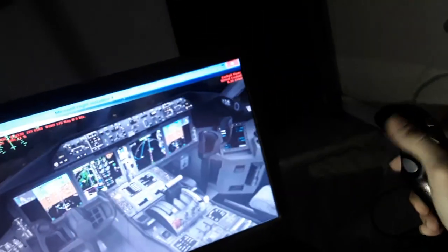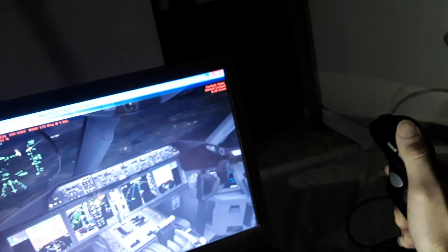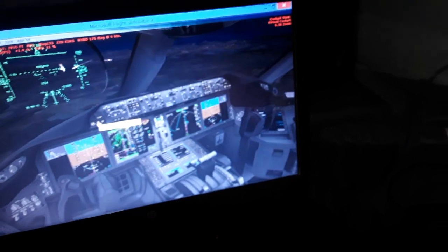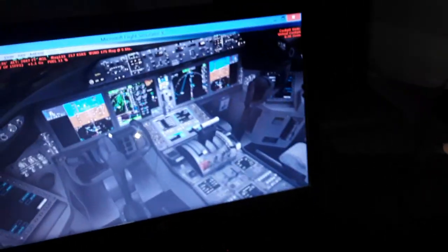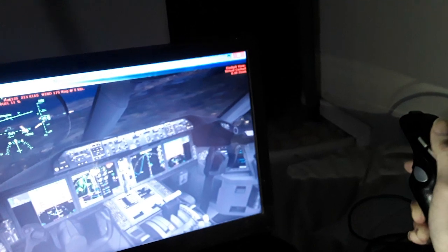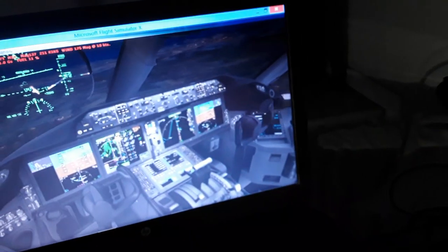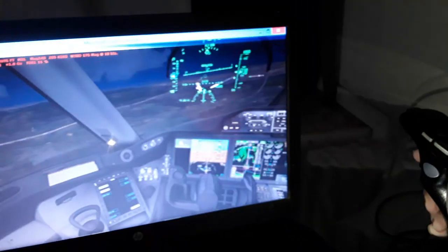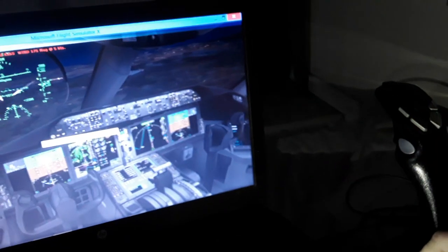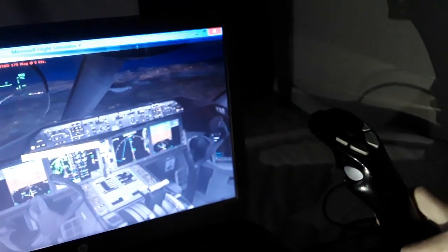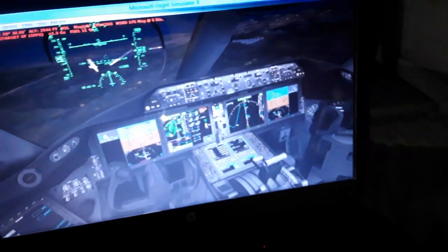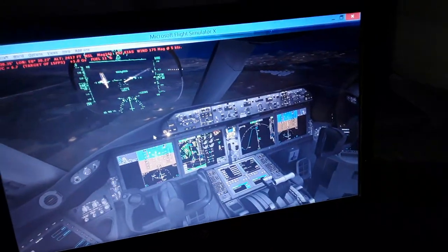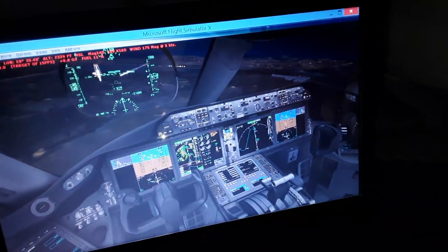So we have some windcast, some side wind, a little bit right rudder or left rudder, and all flight controls coordinated to fly for alignment with the side wind, as you can see in the windcast with the runway heading. So we have 1 more minute left for approach and landing. Use a little bit more airspeed, more thrust. So we have to align the aircraft with the runway if we have side wind like this. We have to decrease also the altitude.